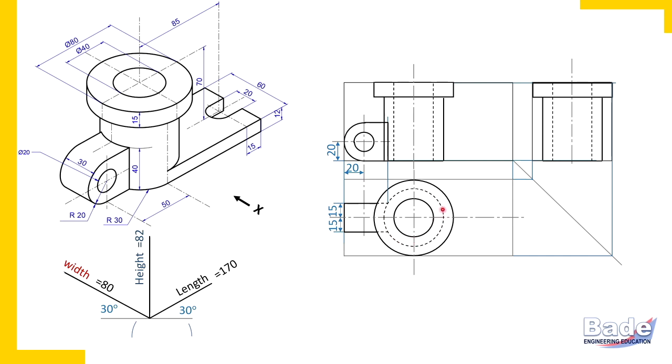The cylindrical surface, this dotted line in the top view is the cylindrical surface, but watch in the front view. This cylindrical surface has boundary generators which we have made dark in the front view. But check here, this curved surface, the cylindrical surface, is only above the U-shaped block, not below that. This end generator or boundary generator is a boundary of the curved surface, and the curved surface is only above the block.